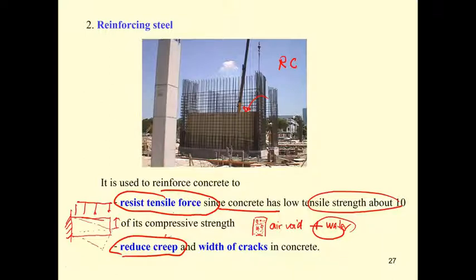One of the things is you got to put the steel into this portion in the proper amount. The steel will help the concrete take care of the leaching out of the water, and the creep can be reduced. The same goes for reducing the width of the crack. We have the temperature steel, because the change in temperature of the slab produces cracks.